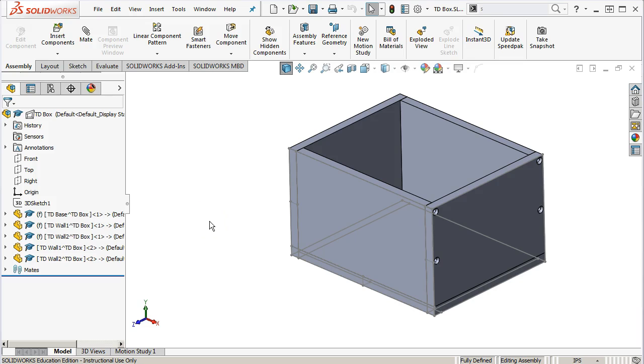If I'm going in with the intention of probably having 3, 4, 5 3D sketches to define my geometry, define hole locations, port locations, something along those lines, then I would probably just go ahead and build everything out as 3D sketches and kind of bypass the layout altogether.